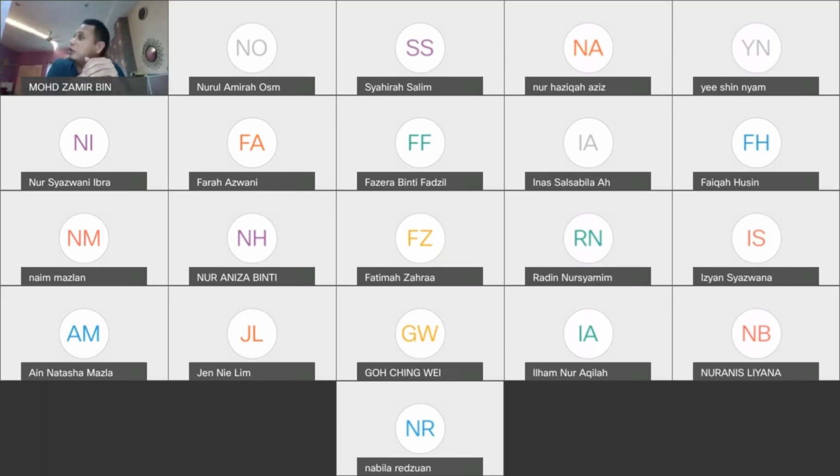Okay, so I'll see you again next week. We'll look at how we do the patterning process by lithography. So lithography is printing by light, as I told you before. Just like how you print your t-shirt here, but instead of using the screen printing process for the shirt, we will print features or circuits using light in the lithography process. We're also going to look at how we do patterning of the oxide that you have just grown from the thermal oxidation process this week.